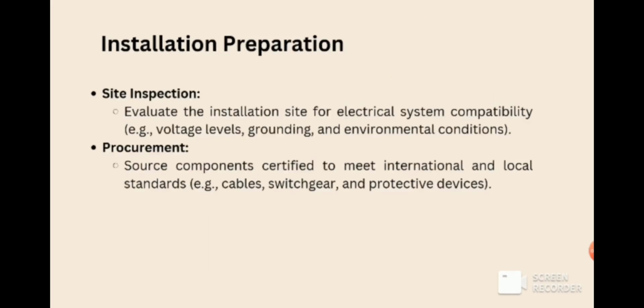The second step is installation preparations. We inspect the site to ensure it's suitable for the installation. This means checking voltage levels, grounding, and environmental conditions. All components like cables and protective devices must be sourced from certified suppliers to meet both international and local standards.